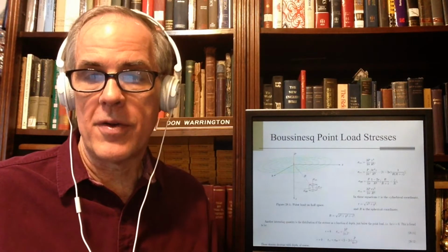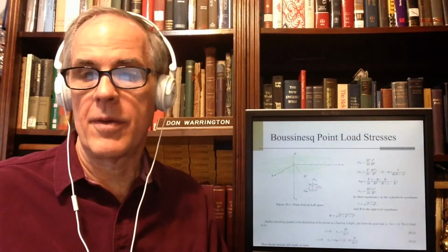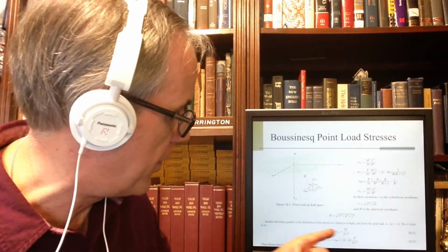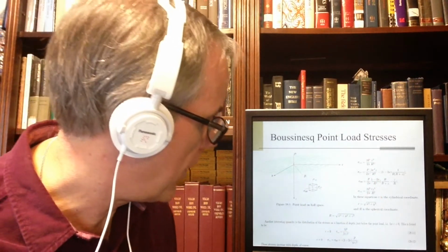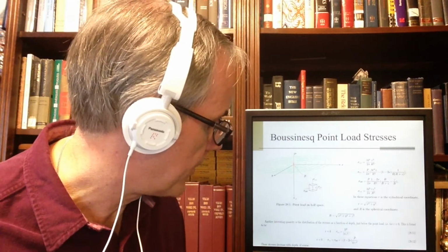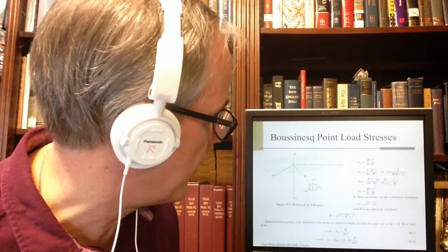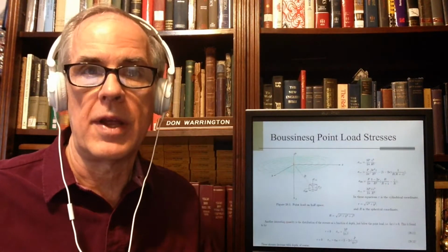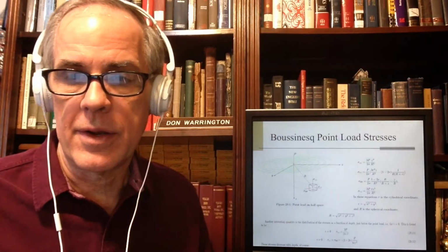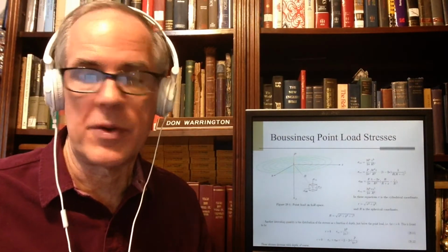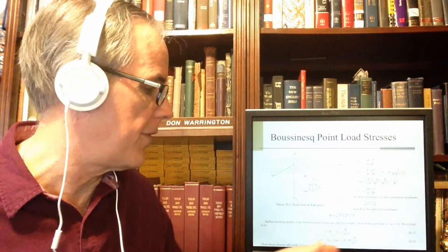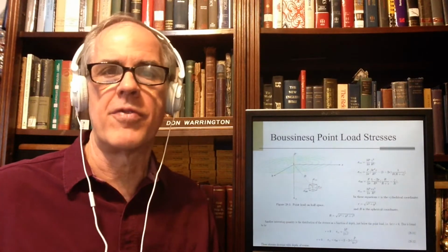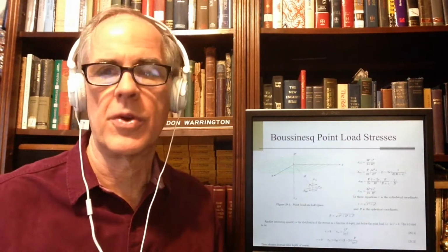There are a couple of equations just below the point load. He actually does simplify this equation to get this one. And also he discovers that your shear stresses go way directly underwards, under the center load, which kind of makes sense. And your hoop stresses are equal to this. So this is the special case under the center, which is where you get your maximum stresses anyway. Once you get away from the center axis, your stresses will go down.